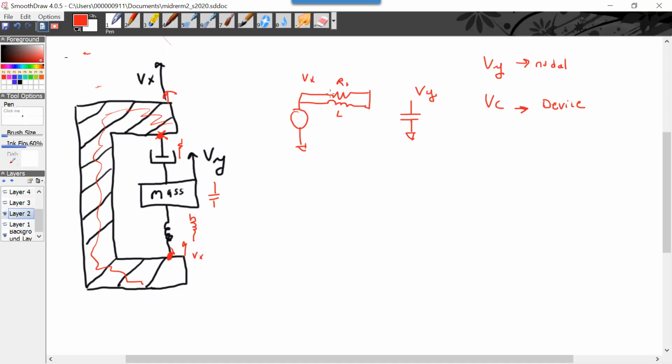And then you can see that the input is connected to one end of the damper, one end of the inductor, and then they're both connected to the mass. Now that might be physical, and you might say, well, one is attached to one side and one is attached to the other. But really, if everything is rigid, I could redraw this, damper here, and get rid of it there. It's mathematically the same thing. This mass really doesn't have dimension mathematically.